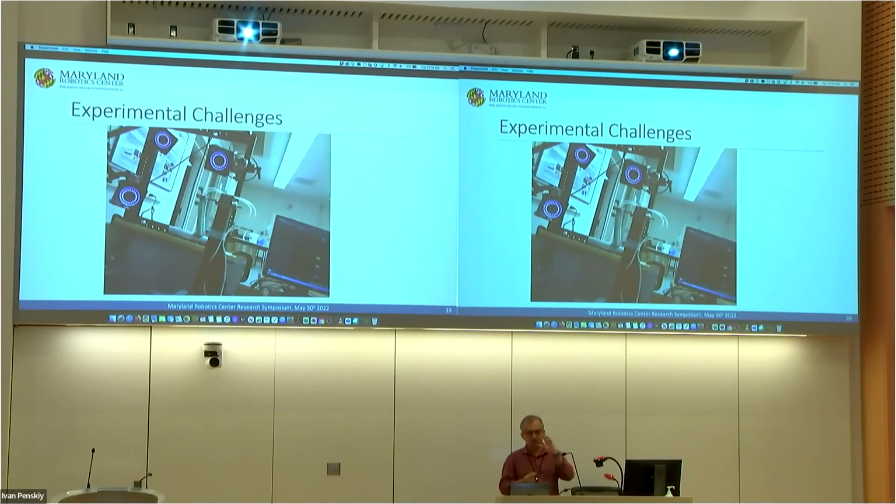At the same time, we are also getting some insights into the trade-offs: if I make it a longer link, it's easier to stabilize. We don't have that here, but if I had a board, we have this long stick, right? If I hold it on my hand, you'll see that it's much easier to stabilize if it's a taller stick, okay? If I make this tall, the problem is that I have to actuate it using pneumatics. It becomes more challenging, right? So there is a power density I want, and at the same time, I want flexibility. So these trade-offs between the design and the control really impact a lot of things in addition to just control algorithms.